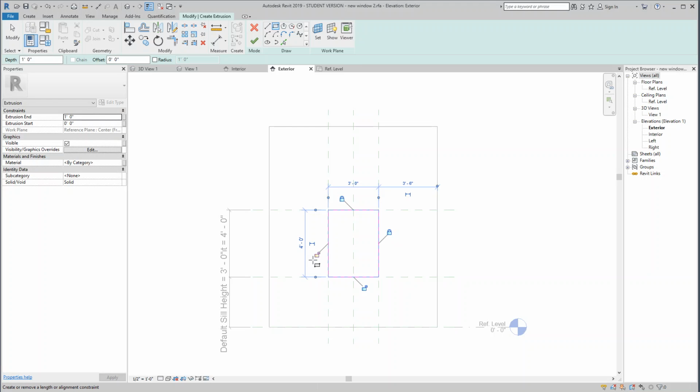And I'm going to go lock those back. Now those are parametrically linked to those. They'll stay engaged in those no matter what happens. But we really want our extrusion not to be a solid object. We want to have a little offset to it, a hole in it. And I've got it already set for 2 inches. So I'm just going to walk around until the dotted lines are on the right side. And then I'll go ahead and join all of those lines on the inside.